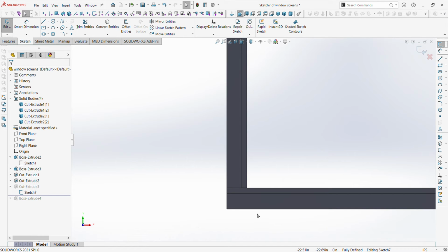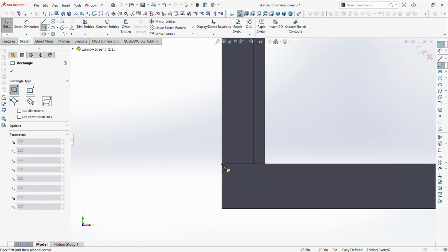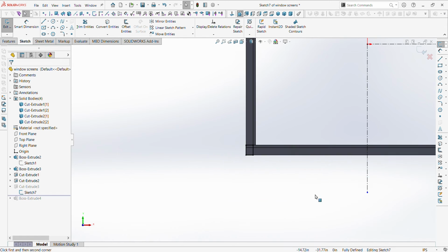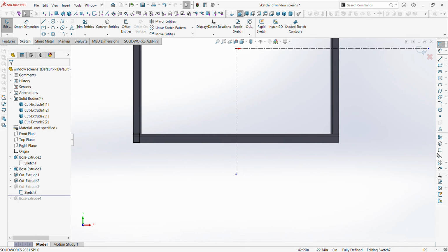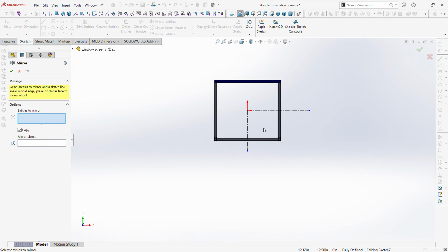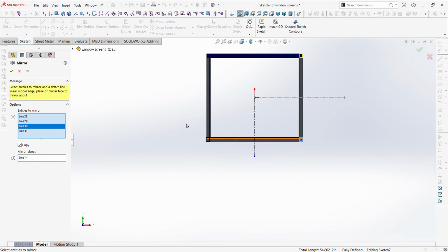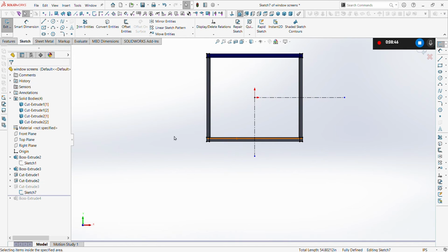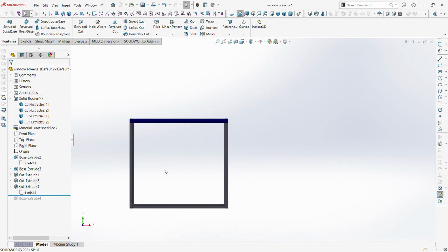Alright, focus here. Rectangle. Press the R button. That's why I gotta go from this point. Come on, give me that intersection. There we go. I'll make one over here. Mirror about this. Mirror this about this. Oh, almost did the same mistake as before. Grab that too. If I rebuild, it should be correct.